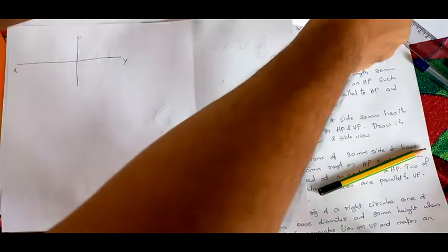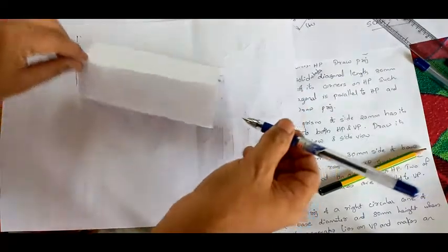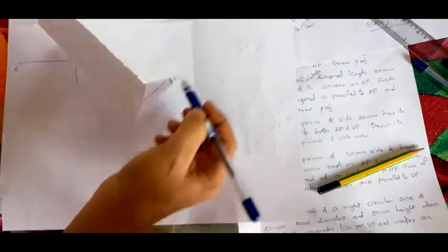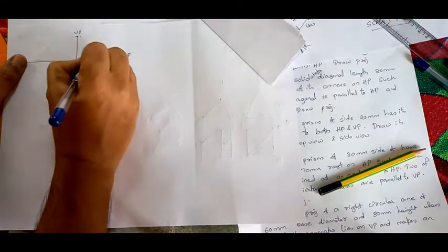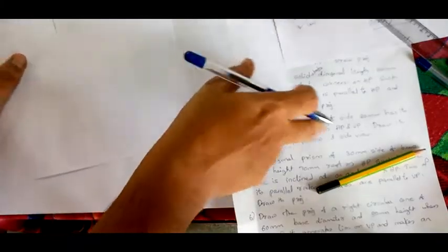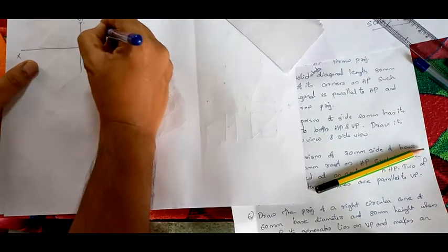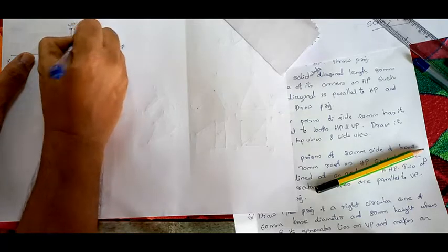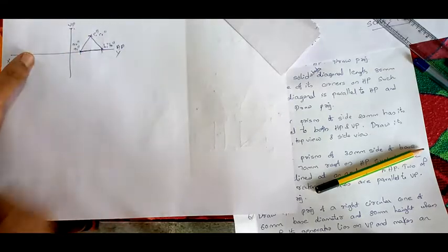Now you have already seen that it is resting like this, that is the side view. You can see the triangle. In the side view, this edge is resting on your HP. So in the side view this will be your HP and this will be your VP. One of its sides is resting on HP, already given, that is a triangular prism of side 20 mm. So draw the side. Now take 20 mm each and construct the equilateral triangle completely. So this will be your A1 double dash, A2 double dash, this will be your B1 double dash, B2 double dash, this will be your C1 double dash, C2 double dash.